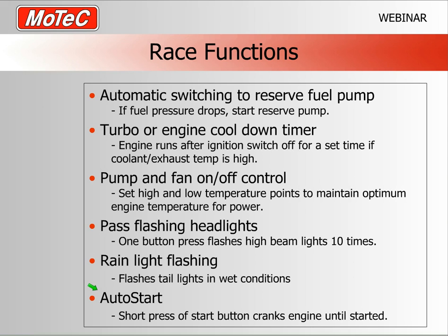Another simple but very practical feature is an auto start function. The point of all of these functions is that they can be customized and programmed by you, so they're not obligatory, but you can have all of this flexibility built in. The auto start function simply allows you to press the starter button, and the engine is cranked automatically until the ECU detects the run RPM, at which point the PDM will stop cranking the engine.